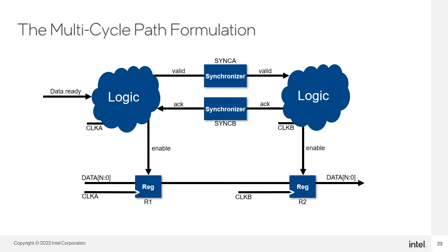But you'll still need to put a false path from R1 to R2 through either the set_false_path constraint or the set_clock_groups command. Once timing is cut from this path, you still need to timing bound this path, and the set_data_delay constraint is perfect for this case in the event you want to put the data enabling logic, such as a multiplexer, in the path between R1 and R2, as the set_data_delay will go through logic to its destination. Starting with the Intel Quartus 21.3 software, the set_false_path command does not override the set_data_delay constraint.